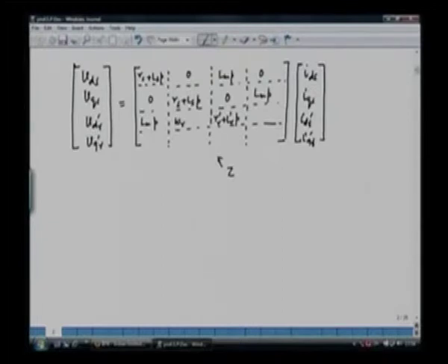So we have omega r here and omega r, and this will be coupled to IQR. So we have LR prime in this case, and this is LM from the stator side. And for the 4th row, that is for VQR, we have RR prime plus LR prime P. Then we have coupling from the stator side. Then we have the rotationally induced EMF minus omega r LM and minus omega r